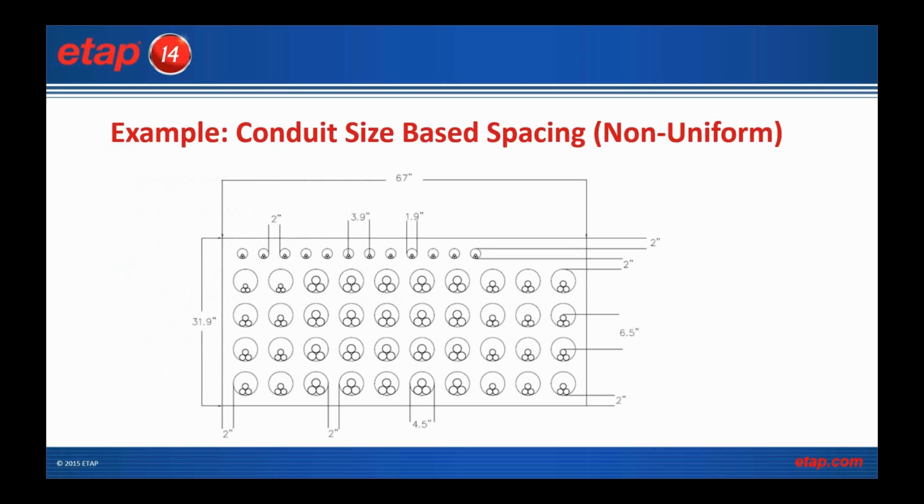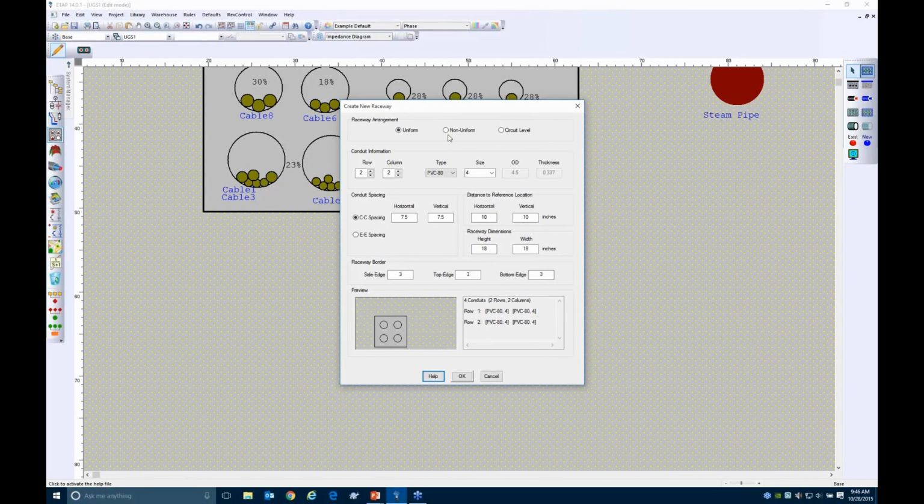And then there's also another consideration that we have to look at later on, which is the type of current or signal that's being carried, whether it's power or control or communication. So we'll cover that in a little bit. But here's a case where I just have power conductors, and they're different sizes because maybe they are for different voltage levels or for different size of equipment. So how would I build something like this? I have a 2-inch edge-to-edge spacing on my first row, and I have a 6.5-inch center-to-center spacing here. So let's just give it a shot real quick, what we would do here.